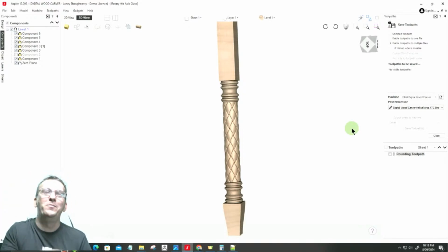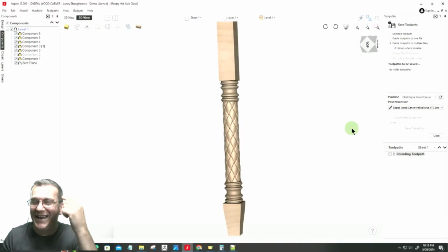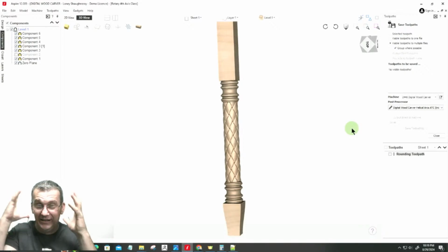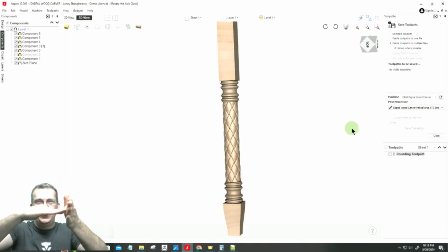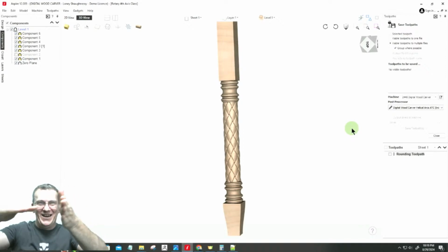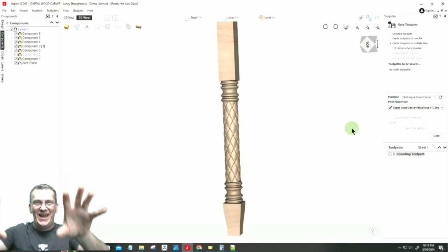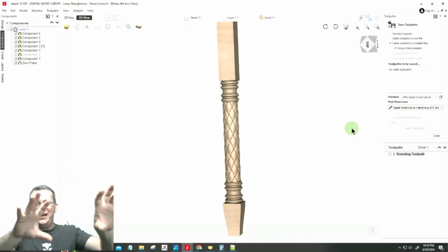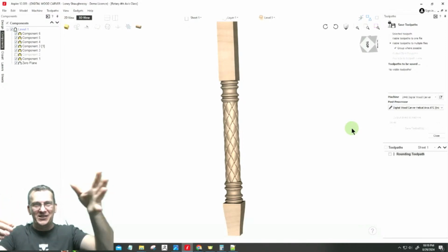And that was my most complicated thing on the first go around, wrapping my head around the axis change, the letter change, and what axis is what. This is now Z, because going to your stock and from your stock is your Z-axis movement, regardless of whether I'm on the table or on the rotary axis. It's still the Z-axis in and out. But it's traveling on a different motor now. When I'm in fourth axis mode, there's a different setting, and it travels along the Y-axis rods to go to the stock that's mounted on the side.